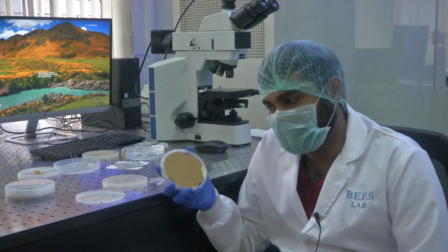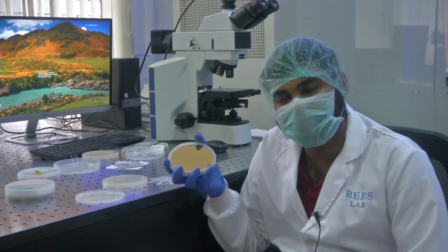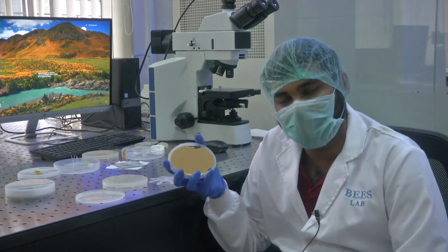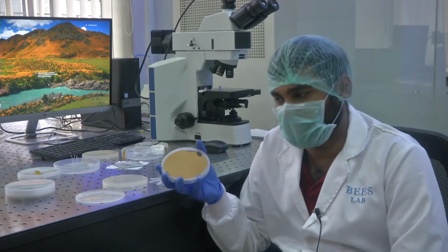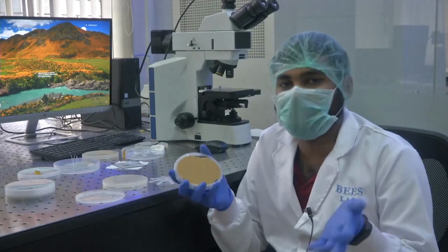So we have a gold deposited 4-inch silicon wafer. The wafer thickness is 500 microns, or 0.5 mm, and the deposited gold is 195 nanometers of gold with 25 nanometers of chrome. Okay, this is one silicon wafer. Now the next thing we do is pattern on this and make our sensors, correct.